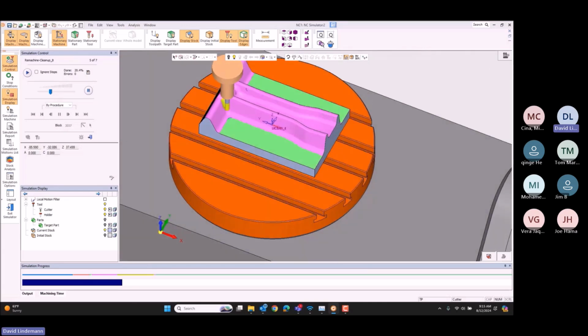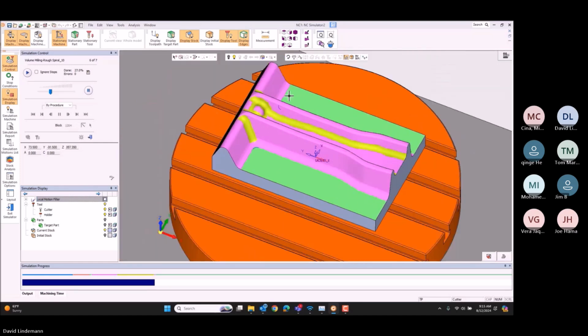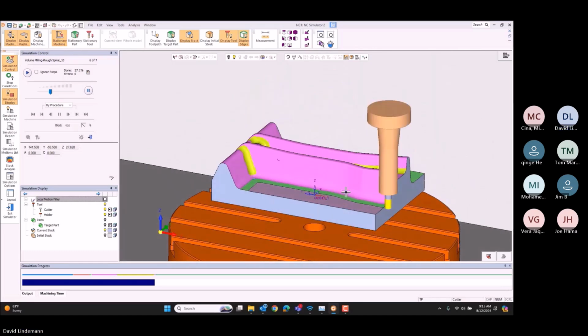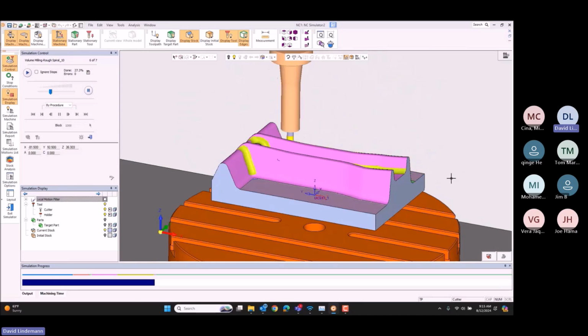All right, here you see it Z leveling a corner, and then you'll see it go across top corners like through there, and now that's doing a nice collapse cut where you can actually see the motions on it. All right. Finally, we're into our finishes. And through it all, we haven't done anything. We have no errors showing up on each step. So all in all, we could say that with the simulation and the verification we're using, it's going to be a nice, clean series of tool paths that we could post now to the machine.